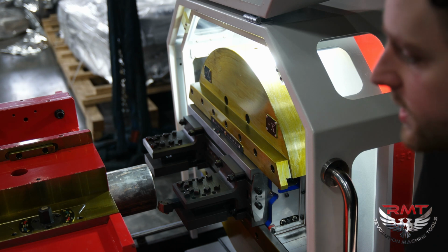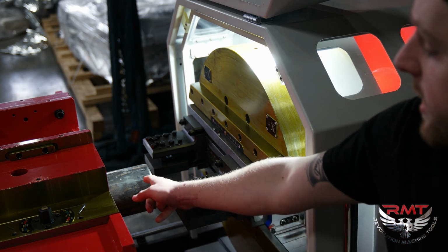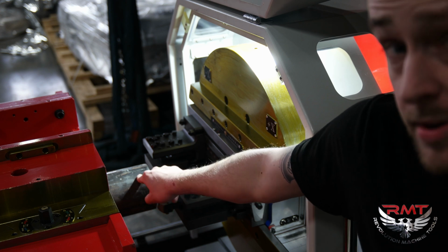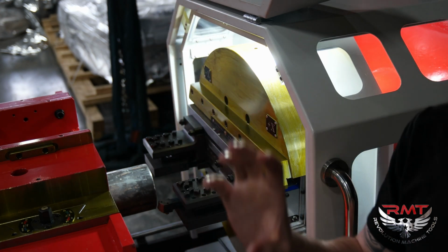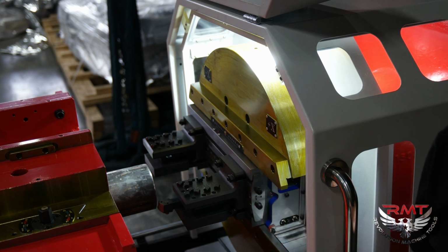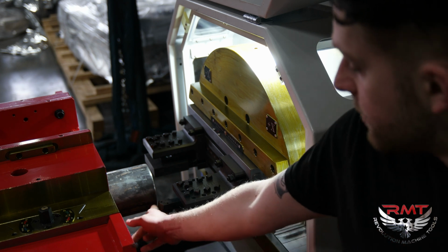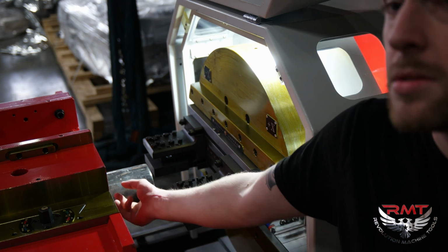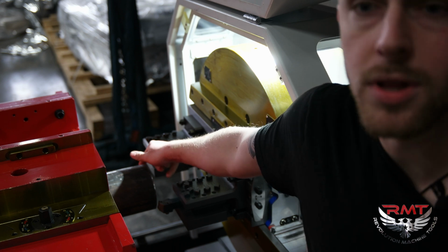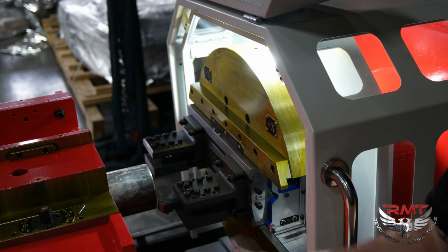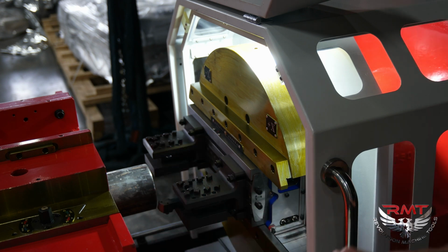The reason for this is, one, if my material is not perfect, it might have low and high spots and stuff like that. So when I go to start cutting it, if I get it real close to this edge, if this is the low spot and say over here is the high spot, then it's going to dig really hard, and we're going to have a similar issue as if the vise isn't concentric, right?